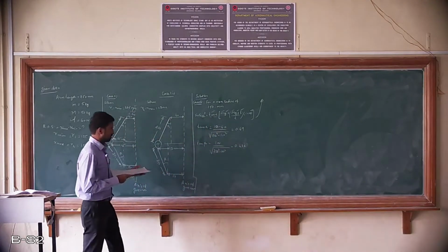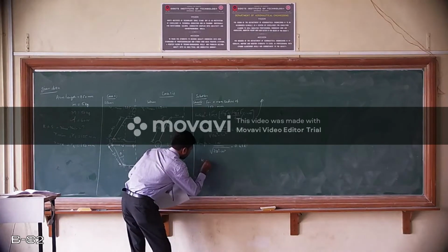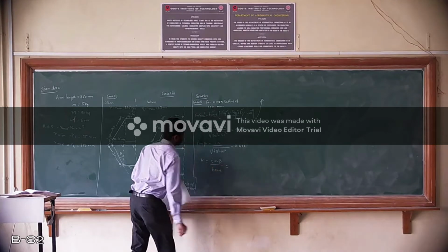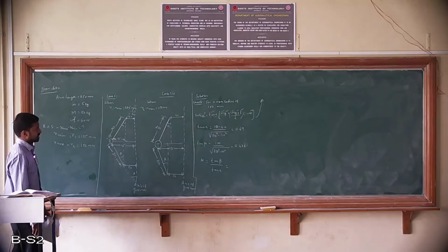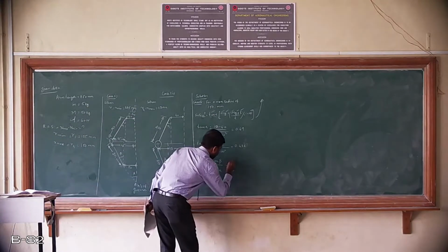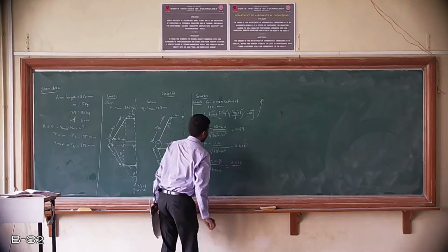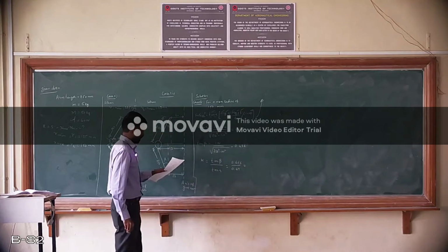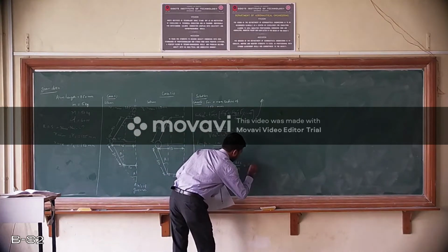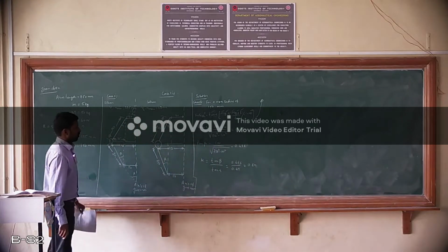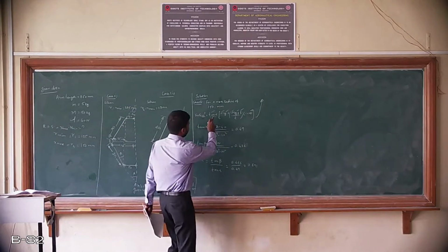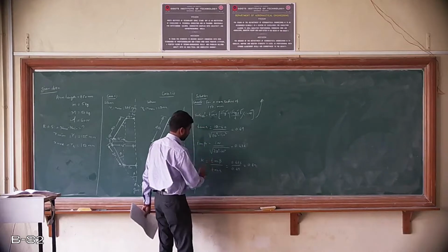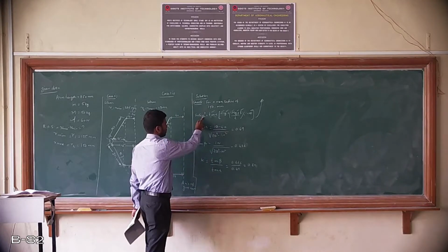So you can calculate the value of K as tan beta divided by tan alpha. Tan beta is 0.436 divided by tan alpha, which is 0.49. So you are going to arrive at the value of K as 0.891. So in this governing equation, we have calculated the value of tan alpha, and we have calculated the value of K using the equation tan beta by tan alpha. Now the remaining unknown is only omega.